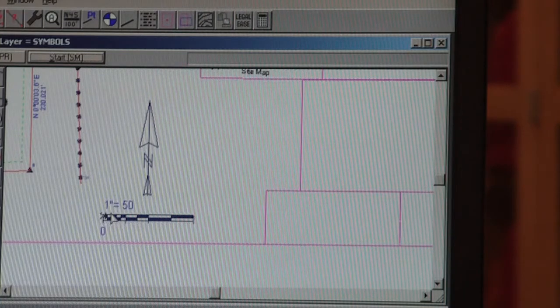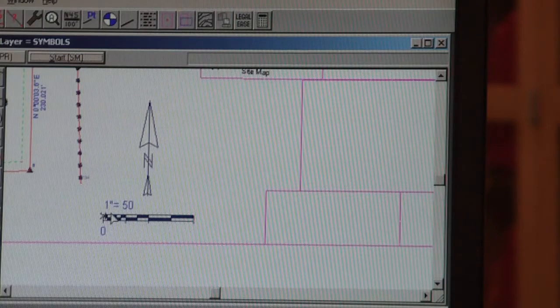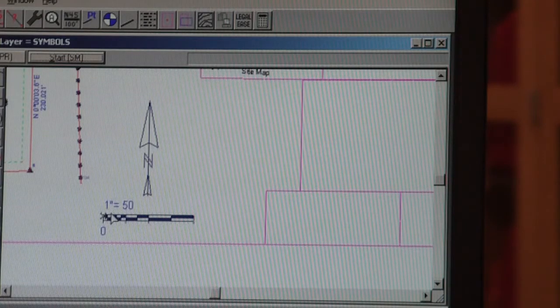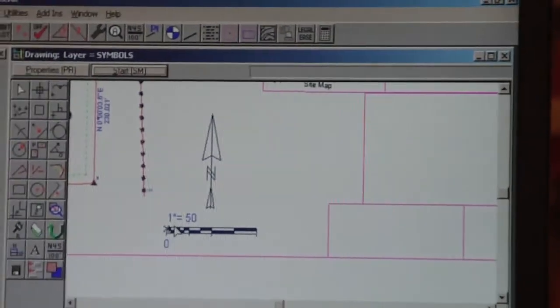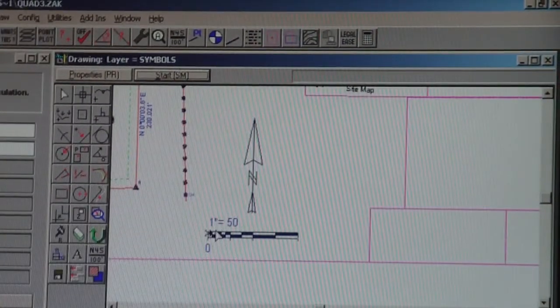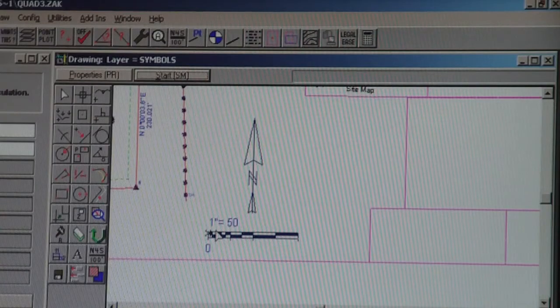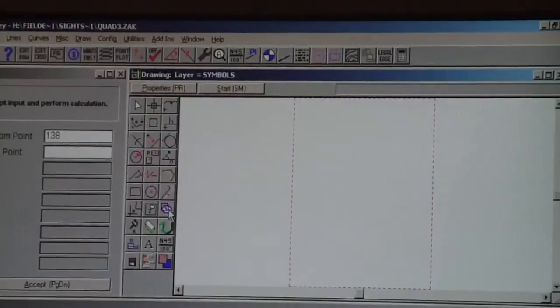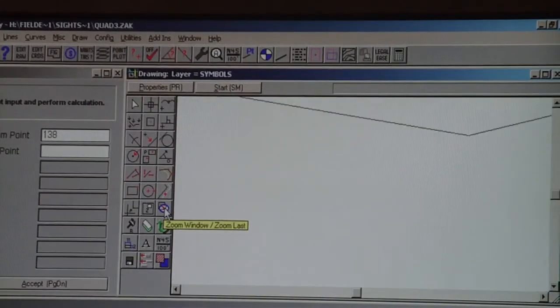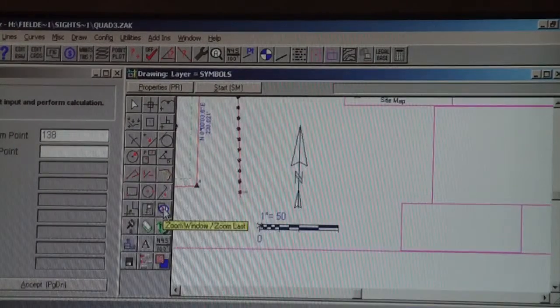So if you scale off of a half-size set of drawings, for estimating purposes, you don't want to have a very precise estimate because you're not going to have one. In other words, you cannot trust the scale. You can't divide it by 2, so thinking that's a 1 inch to 25 feet, it won't work. It'd be a very poor method of estimating. So don't ever scale a small drawing. But I want you to put this on here, so that's what we've got.